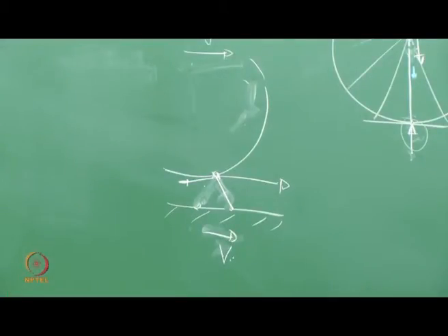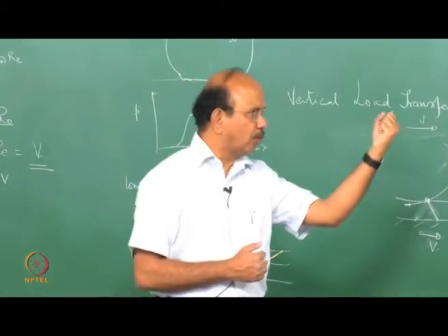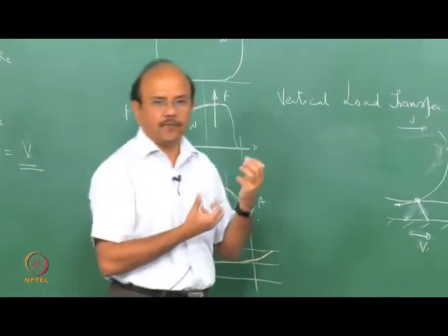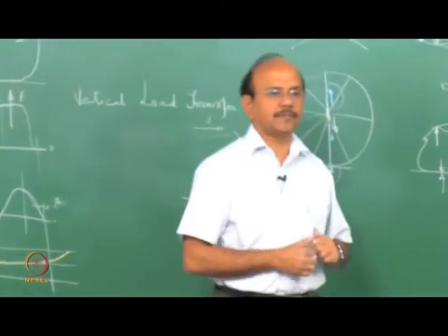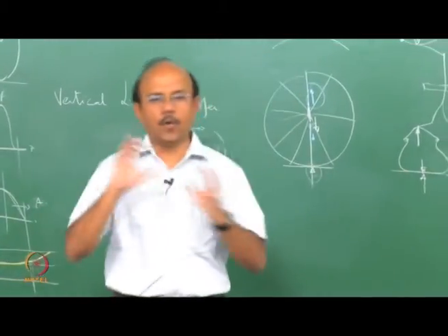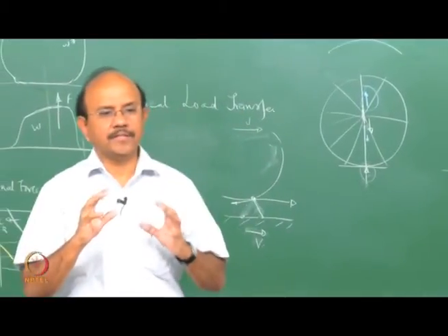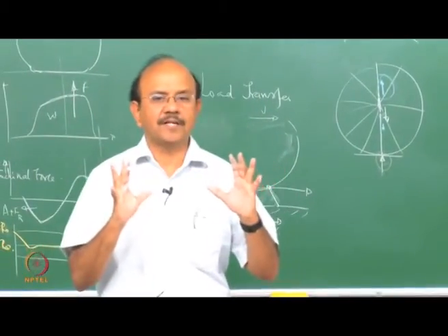Stretching in one direction gives the braking force, and stretching in the other direction gives the traction force. So it is this stretching, however you view it, that is responsible for all the forces developed on the tire.